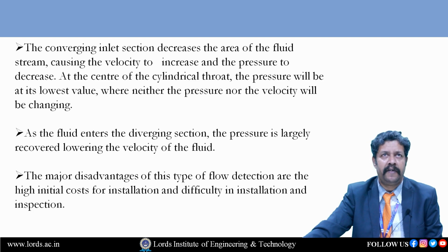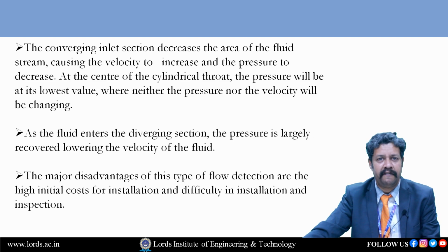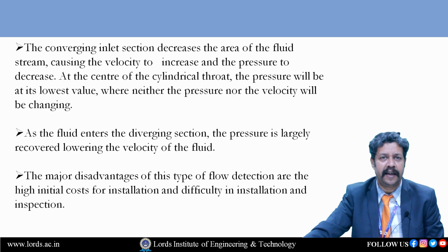Next, whenever cross-sectional area is decreasing, then what happens? Pressure is decreasing, velocity is increasing. So pressure head is decreasing, velocity is increasing. At the throat, what is happening? Pressure also remains constant, cross-sectional area also remains constant, velocity also remains constant.